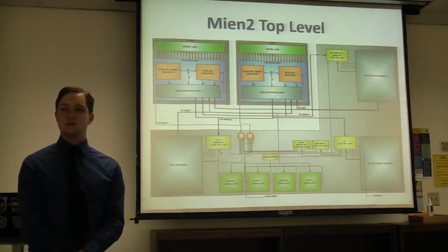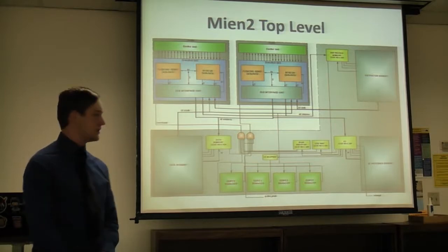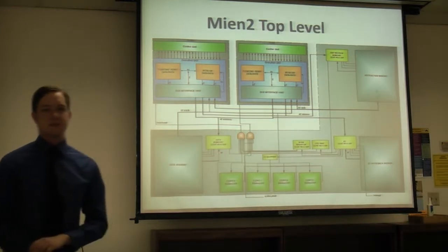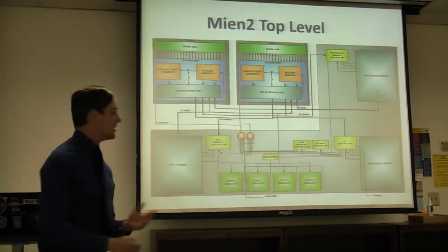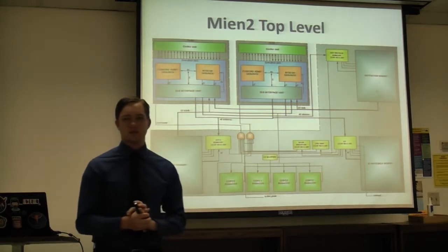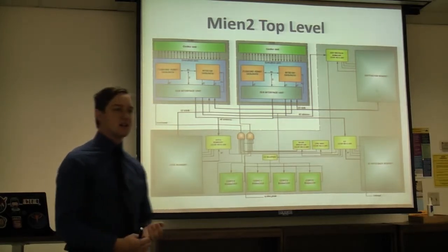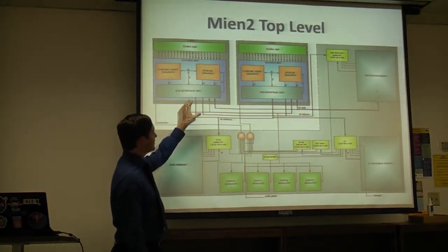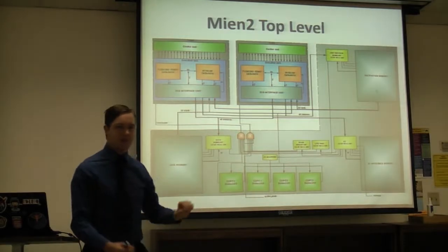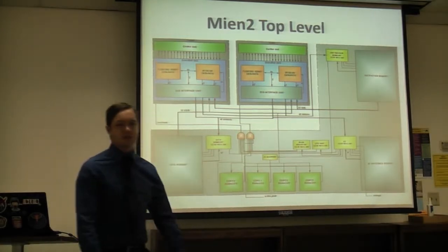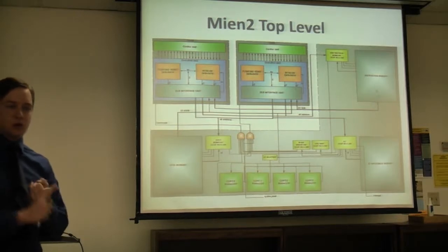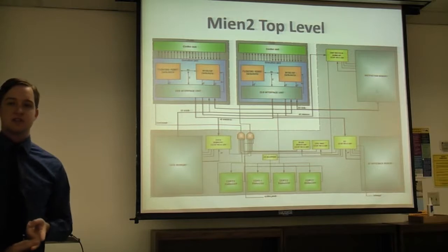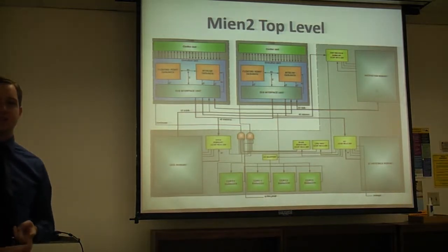Any other questions? Core managers. So they're just boxes to us. What's inside of a core manager? What does it manage? What does it do? Did you have any examples, or how is it implemented? It's just a simple register actually. These are simple registers with a one-bit register saying whether or not the CPU is active and another 10-bit register specifying the reset address of each core.